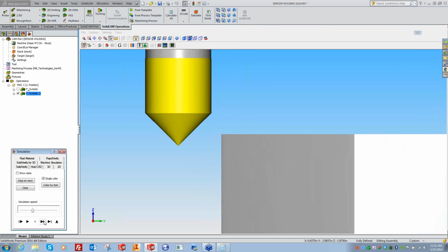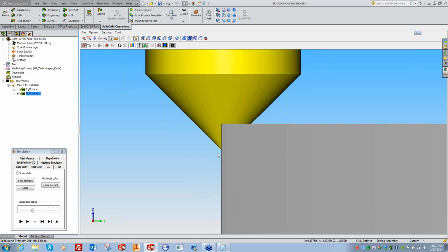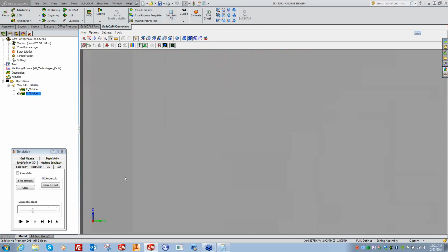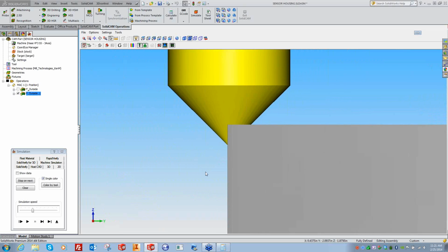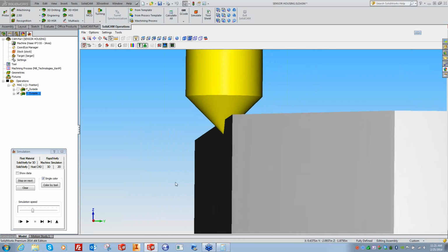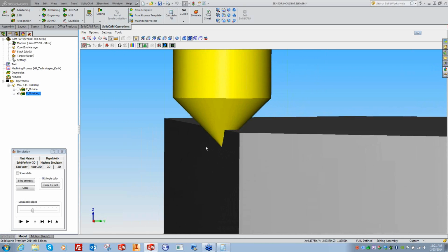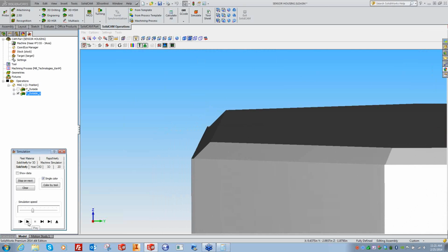Now, as we go down, you'll see that's an arc in right here. Notice you are right at that tip. We did 1 thousandth, so it's hard to see, but there's the tip down there. You're right at the tip of it. Okay, that is a way to avoid, if there was a shelf down here, how would you avoid the tool touching the shelf? Well, you give it a smaller diameter size and it pulls this tool up further. Yeah, maybe I did too much. Did I do a negative or something?